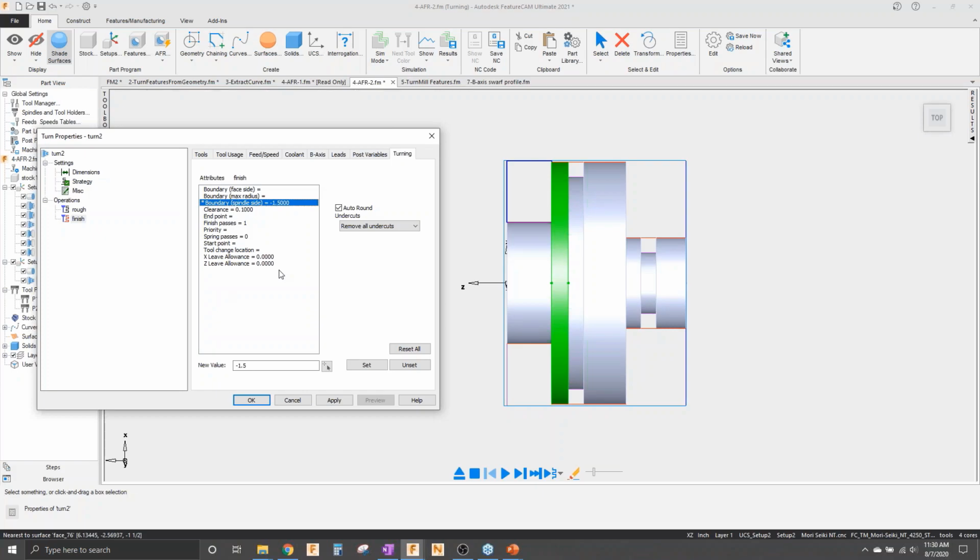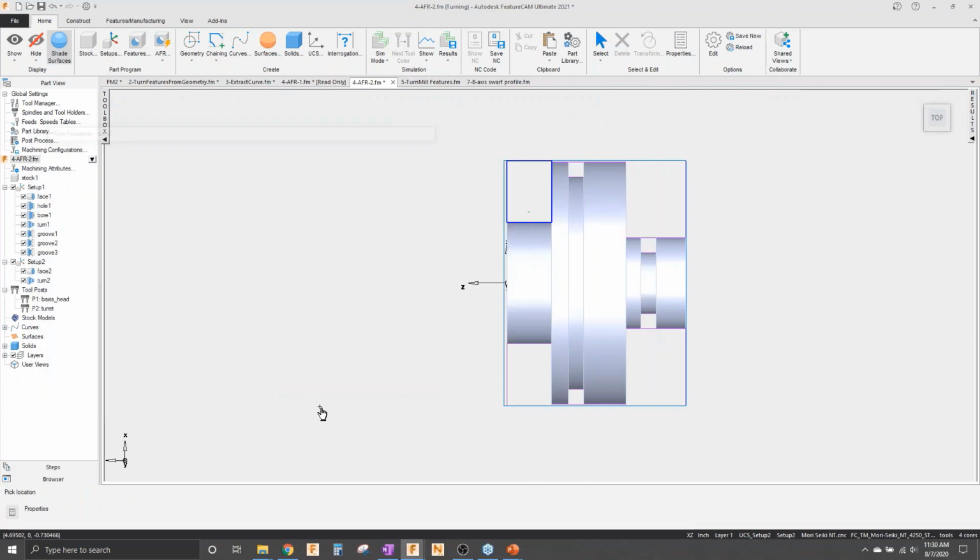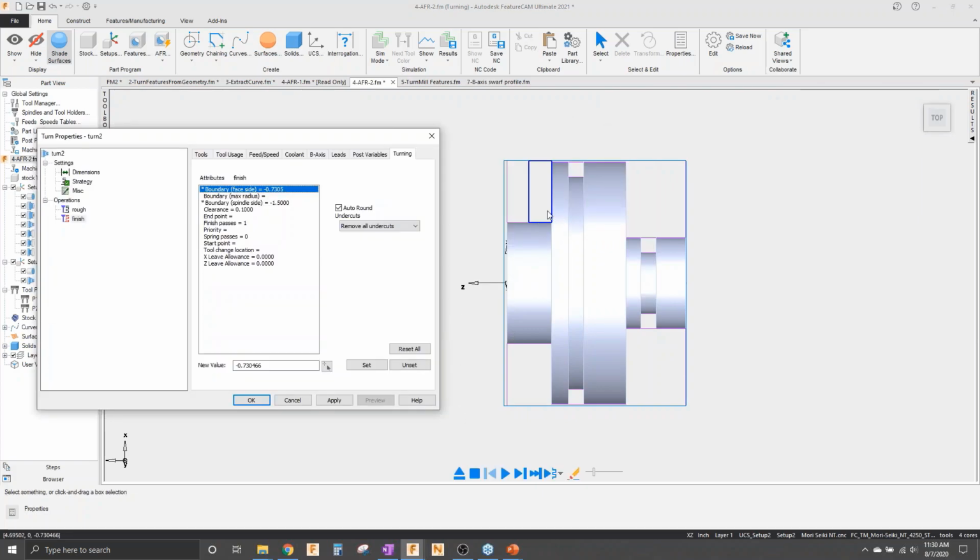So these boundaries are really nice to use because what you can do is you could actually create a curve, and then you could use that curve multiple times and just constrain your tool with boundaries. So say for instance that, say like this was a casting or something, and we just had a little radius to cut out in here. I could actually set a face side boundary as well and go right here somewhere, because I know I'm only trying to rough out a little area here.